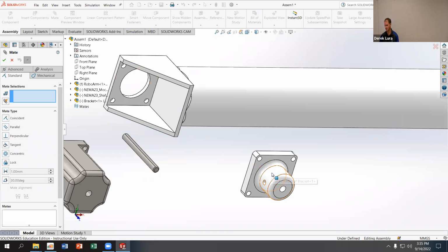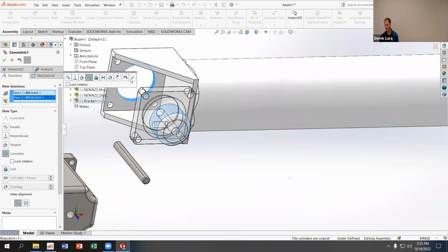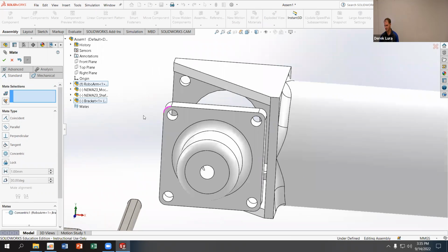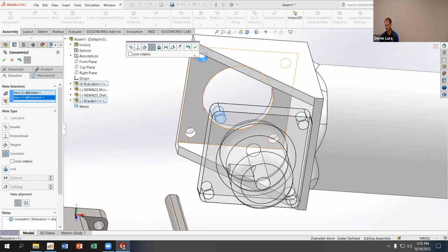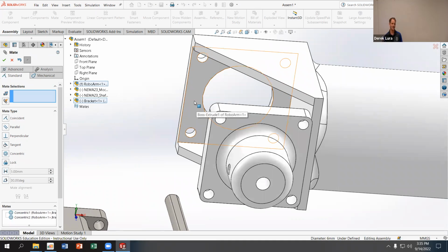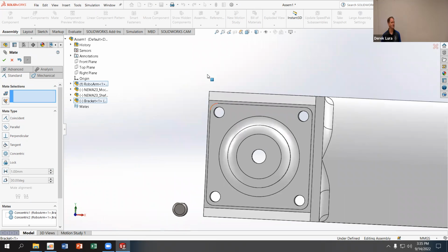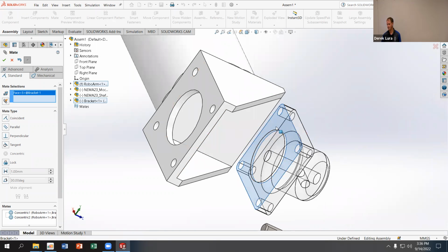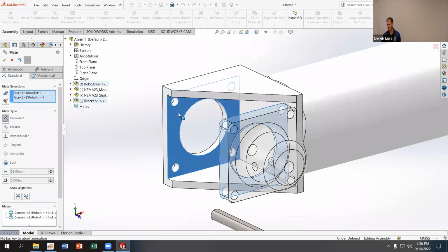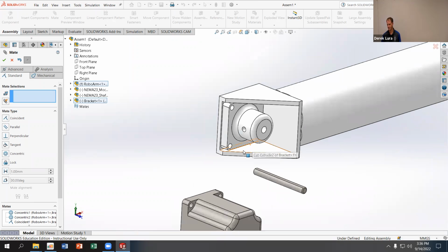So I'm going to mate these in their general position. I'm going to use a concentric mate to put this bracket aligned with that hole there. I'm going to use concentric mates to align just one of the holes on these two sides so it can't rotate. Don't add additional mates. You can. I could add mates for every single combination of holes on here to make them all concentric. I don't need to. You generally don't want to add more mates than you need. I'm going to put the inside edge of that bracket onto the face of the arm. Good?